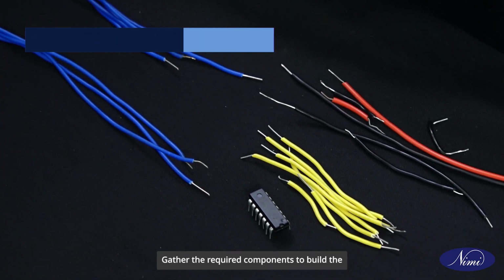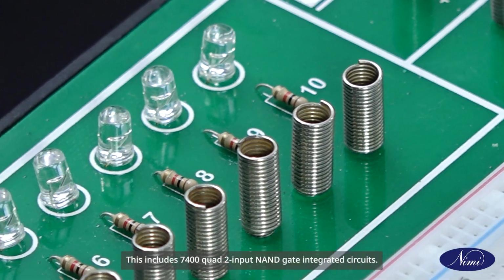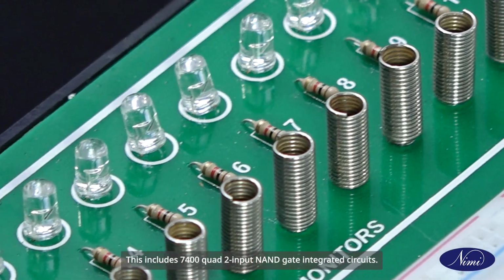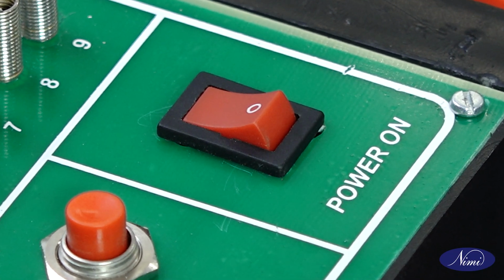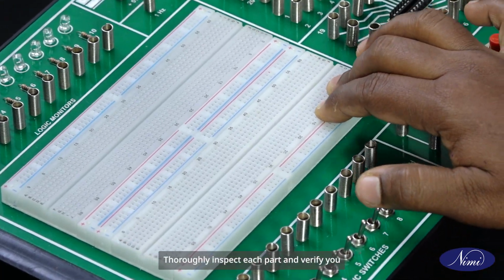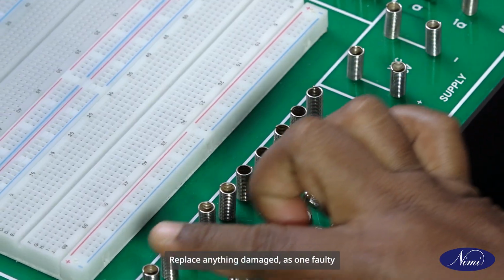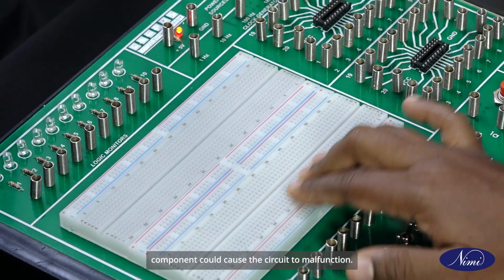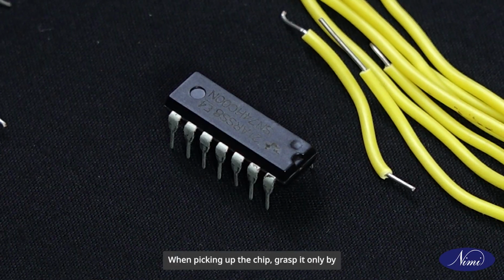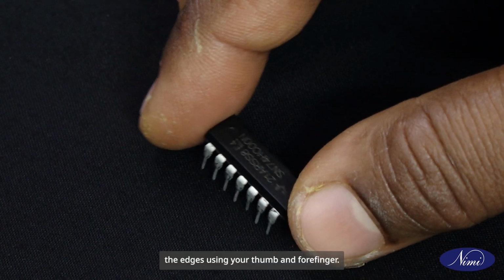Gather the required components to build the RS flip-flop on a solderless breadboard. This includes 7400 quad 2-input NAND gate integrated circuits. Thoroughly inspect each part and verify you have the full set before beginning the assembly. Replace anything damaged, as one faulty component could cause the circuit to malfunction. When picking up the chip, grasp it only by the edges using your thumb and forefinger. Avoid touching the pins.